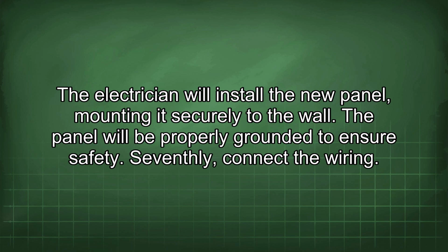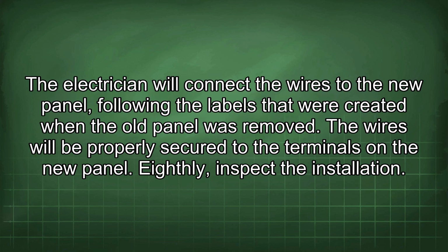Seventhly, connect the wiring. The electrician will connect the wires to the new panel following the labels that were created when the old panel was removed. The wires will be properly secured to the terminals on the new panel.